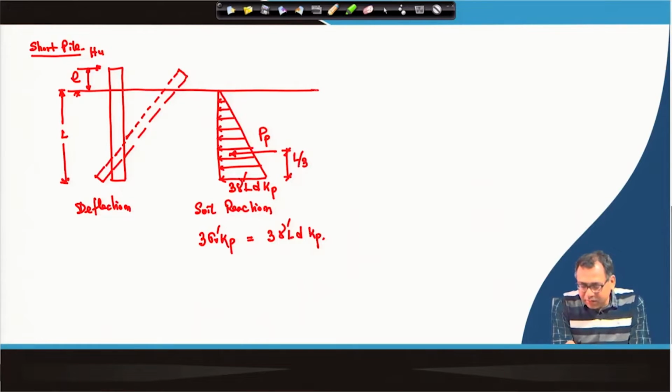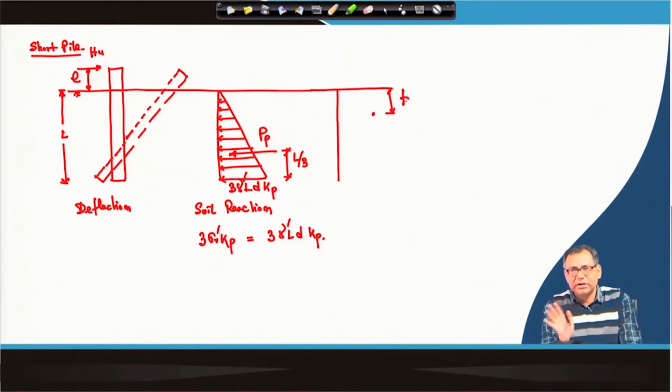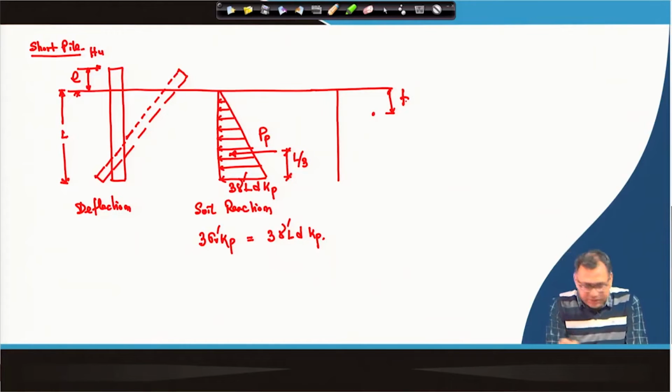Again here also the maximum moment will act at a distance of f from the top, but here no zero earth pressure condition exists like the cohesive case, where the top 1.5 d has zero earth pressure. So, there will be a maximum moment here.